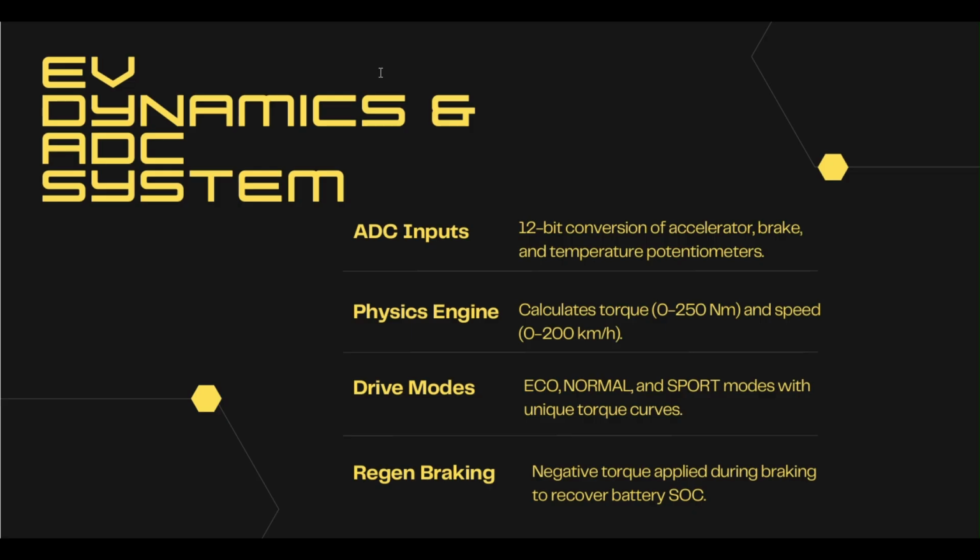Let's talk about the vehicle physics. How we read the pedal. The STM32 uses a 12-bit analog to digital converter. This means when you move a slider from minimum to maximum, the microcontroller reads it as a number from 0 to 4095. Our software turns that number into a percentage to understand how hard the driver is pressing the pedal.